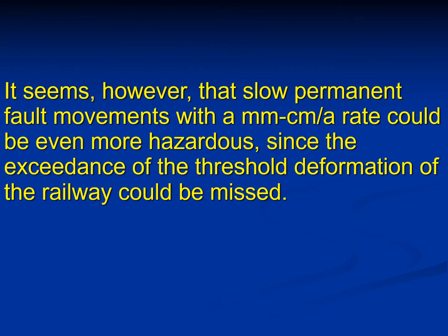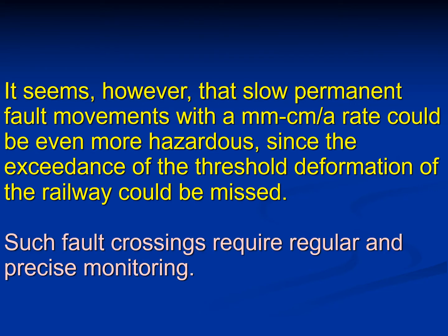It seems, however, that slow permanent fault movements with a millimeter to centimeter per year rate could be even more hazardous for railways, since the exceedance of the threshold deformations of the railway could be missed in this case. Such fault crossings require regular and precise monitoring.